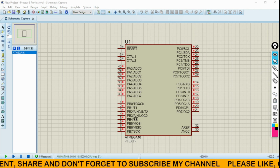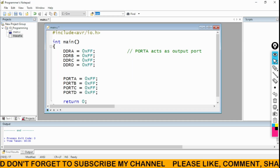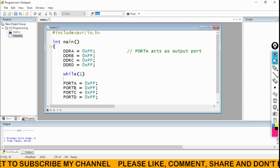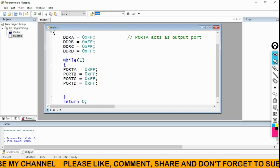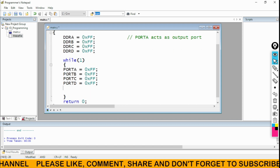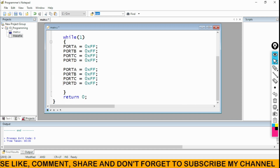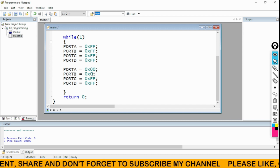Now if you want to do blinking of this port, basically how do we do it? We need to take a while loop in here. It will move continuously, indefinitely, and we are going to set the value of all these ports to 0xFF and then 0x00.